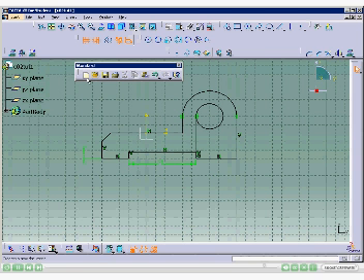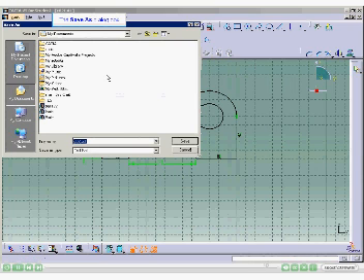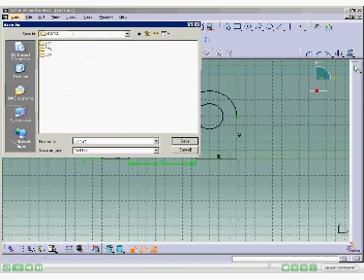After completing the sketch, you need to save it. Take out the standard toolbar. Choose the Save button to invoke the Save As dialog box. Create the CATIA folder inside the My Documents folder. Then create the C02 folder inside the CATIA folder. The name of the file, C02-Tut1, comes automatically in the File Name Edit box, and choose the Save button.